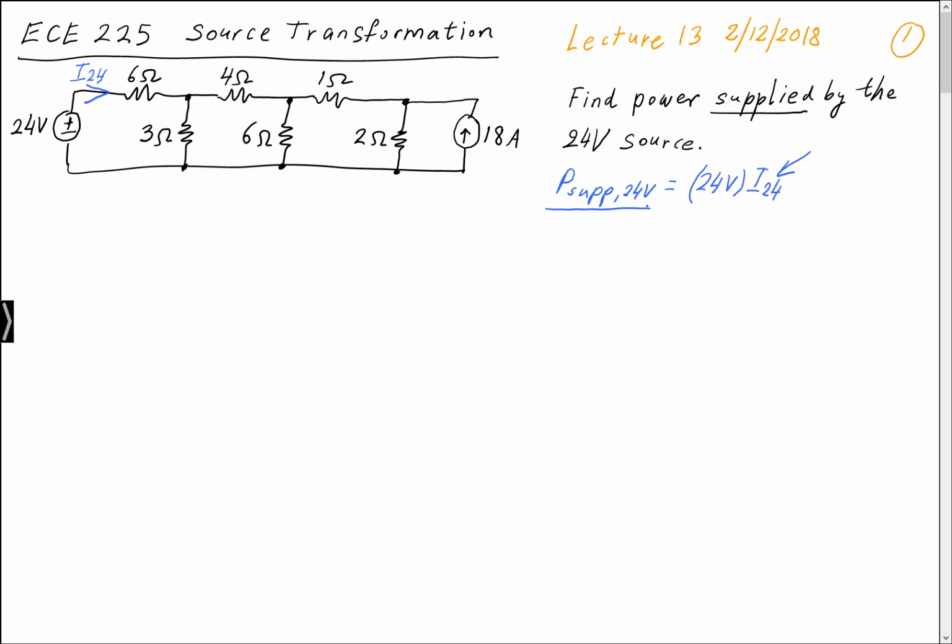So what we're going to do is start on the right and work ourselves to the left. First, we look at these two pairs of terminals right here, and we're going to transform the circuit to the right of that, and then simply redraw the circuit and keep transforming.